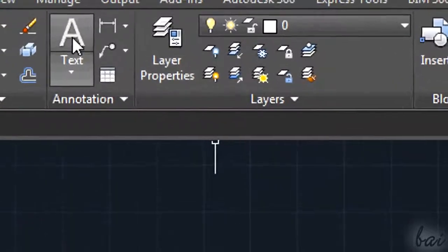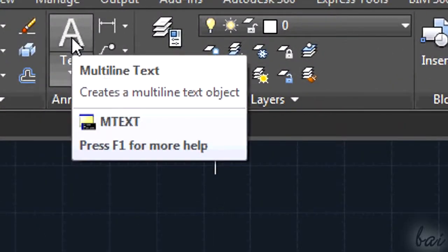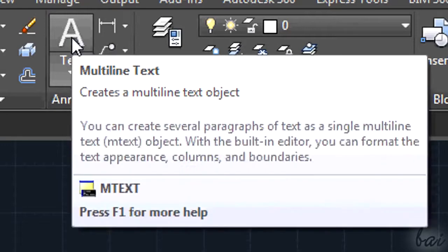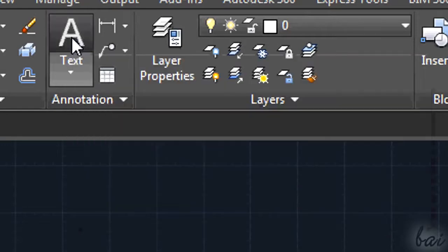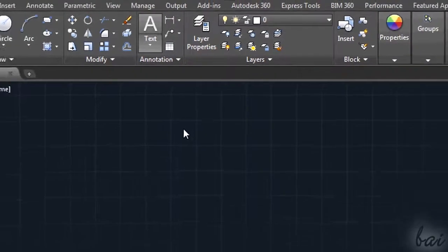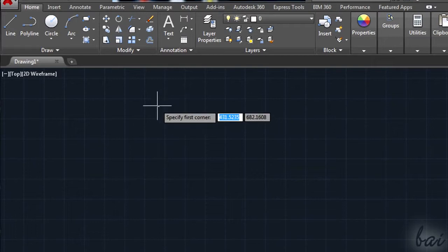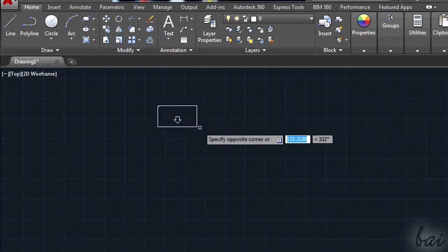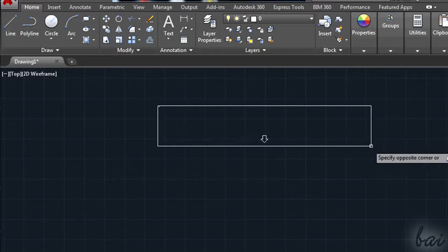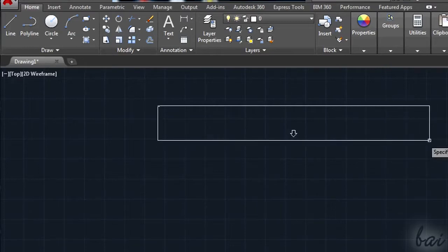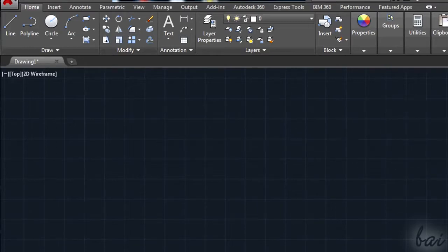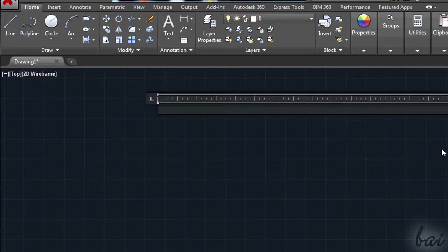What about text and annotations? These are all listed in the Annotation section. You can create text clicking on the A button. Then click and drag to create the text area that will contain text. The down arrow indicates where the text spreads when you make new lines. Once done, set the text style before typing in.